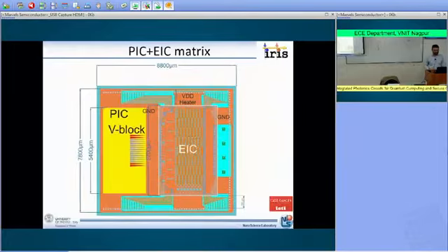And then what you do is that you place the electronic integrated circuit on top of your photonic integrated circuit, and then you place here the fiber array that is used in order to insert and extract the light signal from the circuit. And then you see that the metal wires touch the photonic integrated circuit, and then here you have electrical wires that take your input and output signal from here to the electronic integrated circuit.